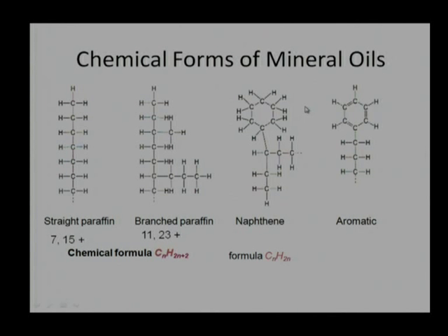So, for low temperature application, naphthenes are good, but they will not have the structural or thermal capabilities to sustain high temperature as a paraffinic oil. So, both have merits and demerits. Coming to the aromatic, what we find are unsaturated bonds. These bonds are unsaturated, and can react easily with other agents, other chemical forms. So, aromatics are least preferred compared to the paraffinic and naphthenic.